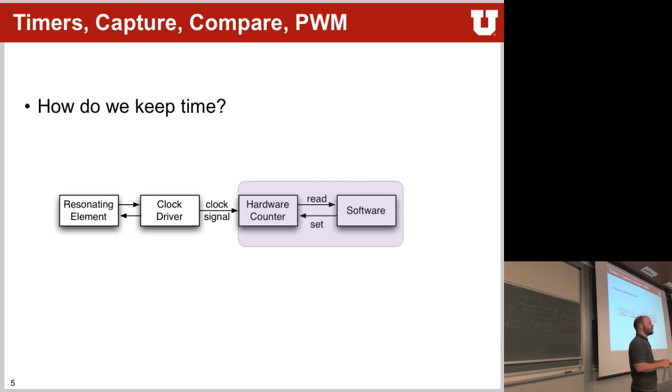Questions to the capture? Yes? If we invert the capture signal, invert this signal, so for example, it's falling edge capture. Yeah. That's possible, oftentimes, yes. And oftentimes you can configure, there's another block here that you can configure and say this is sensitive to a falling edge, sensitive to a rising edge, sensitive to both edges. So there's lots of different configurations. And it oftentimes depends on the manufacturer and the person that made that particular peripheral.